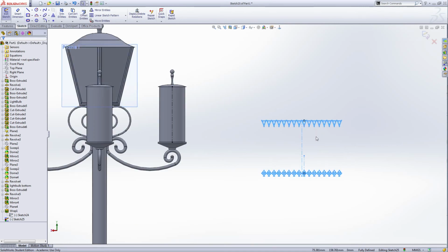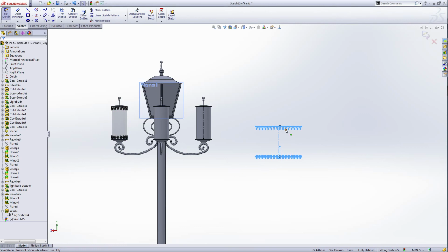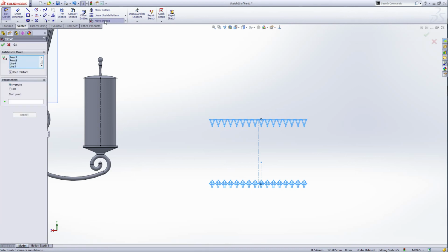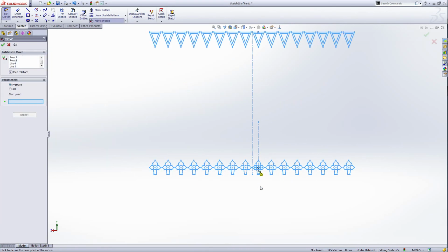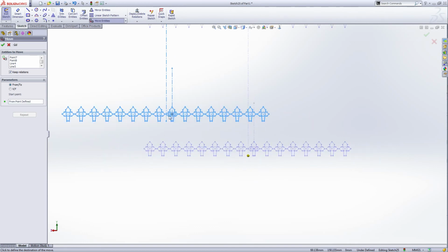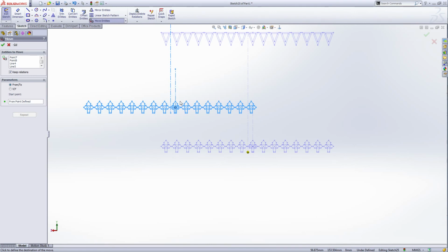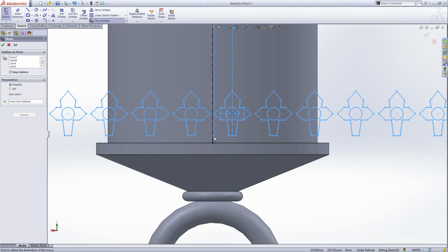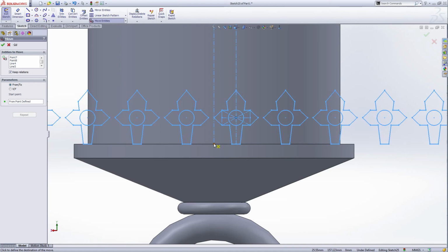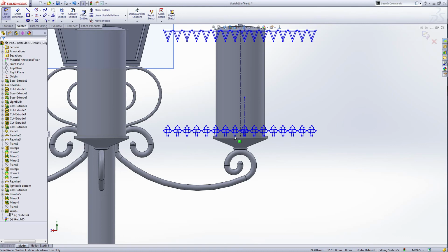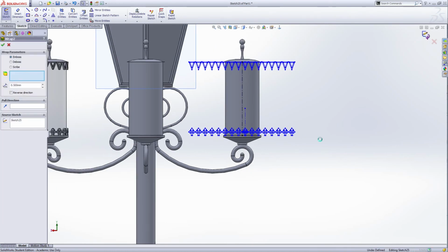We copy the sketch from this cylinder surface wrap feature. Okay, now also use the move entity, and select everything. Move entity: I want to select this point to move from. Okay, so now we can move it. Slowly move it and zoom in, and make sure you put this point coincident with this point and click. And now this is exactly like this one, and exit the sketch.